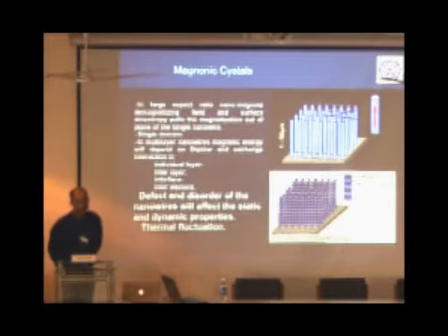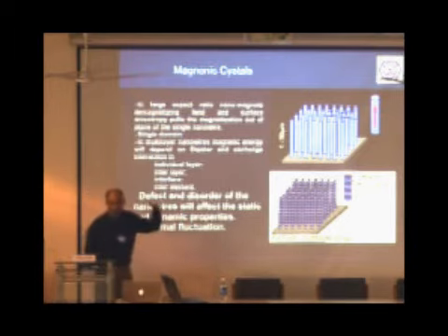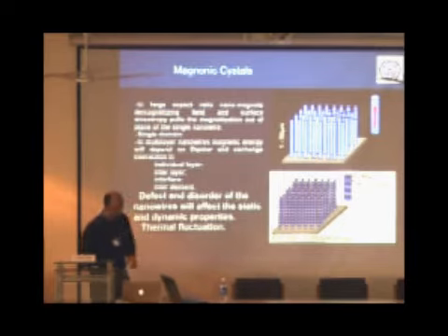Essentially it is a periodic array of magnetic materials in the XY plane as well as, if you decide to make a multilayer, in the Z axis. It is not that easy to make these materials because they tend to intermix. You have to have very sharp boundaries, especially if you layer magnetic versus non-magnetic materials, or put a metal and then an oxide. That is not easy.